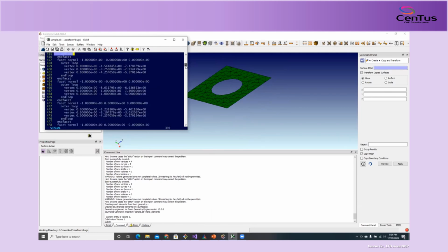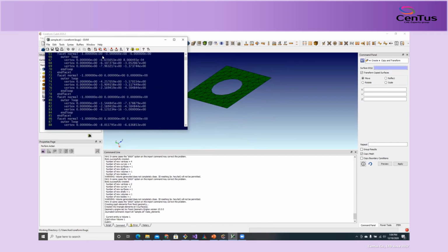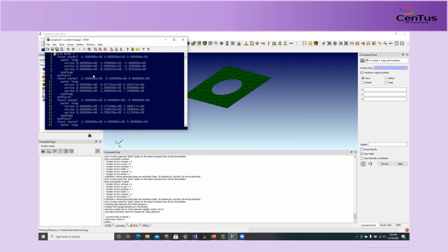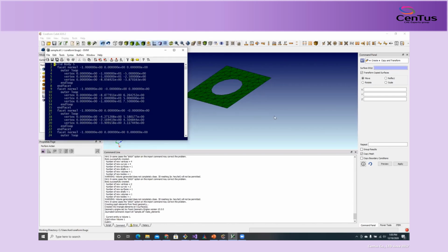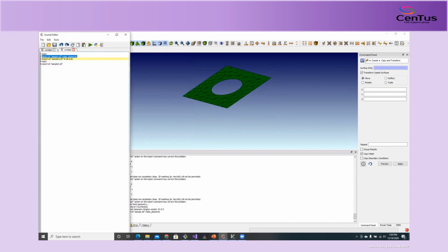And I have multiple bodies defining this. So the fact that I have multiple bodies means when I bring them in, I create them as separate volumes. So in order to work around that, we're not smart enough actually. We don't deal a lot with STL files. That's not our major focus. So we're not smart enough just to know, oh, this should have been one complete volume, even though STL told me it was multiple. So what we're going to do is I'm going to write this out again, and I'm going to export it.